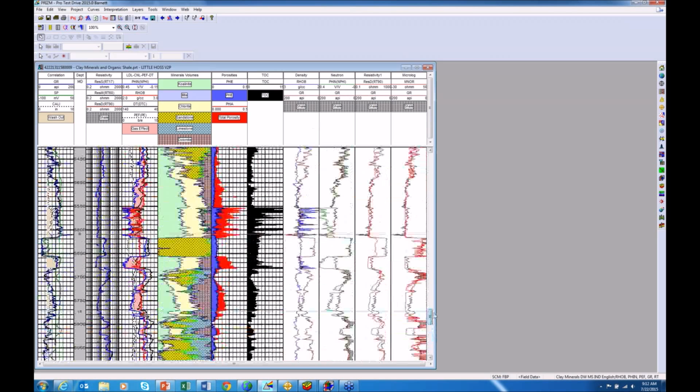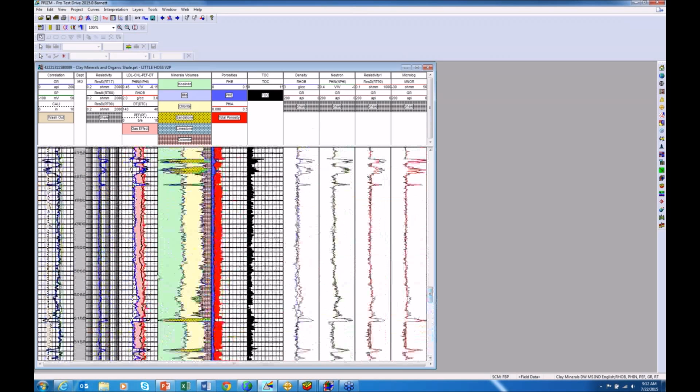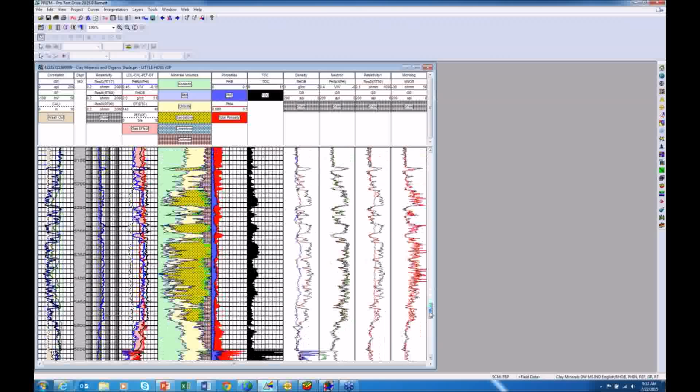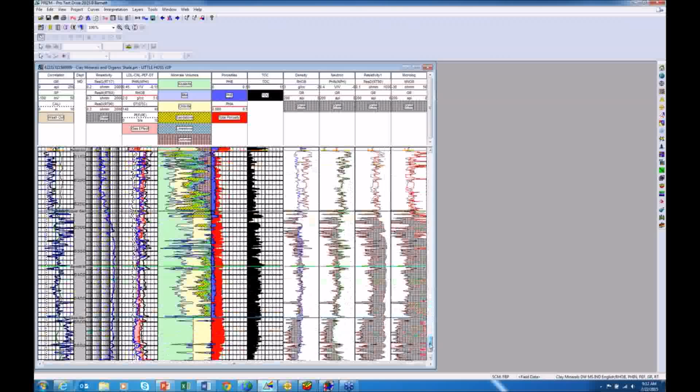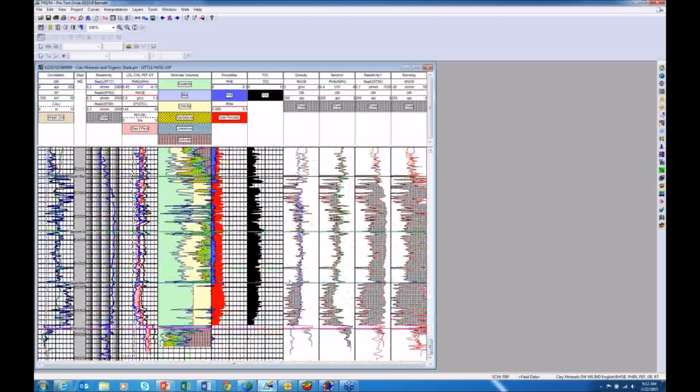And I'm laying those curve scales one on top of the other in an area where I think it is inorganic clay or inorganic shale. Where these curves cross, that's an empirical indication of organic clay. So I think this is a pretty good target. So I want to make this my target zone right in here where I've got the most confident components.